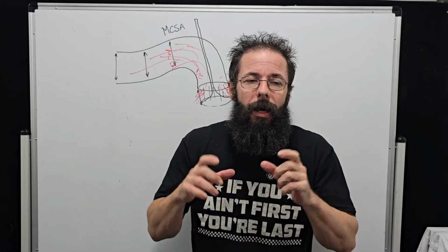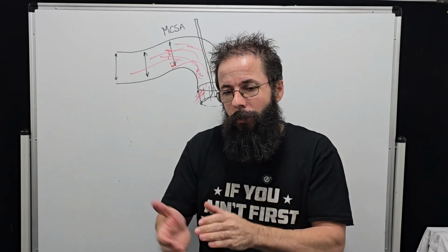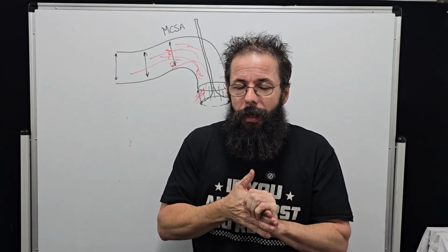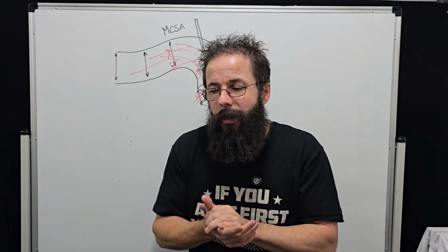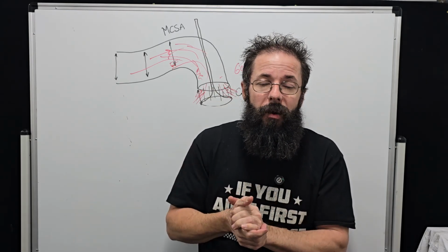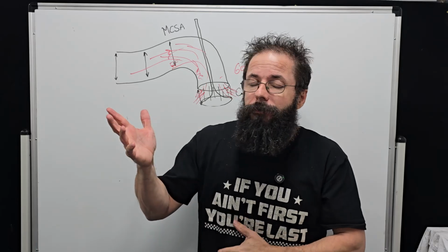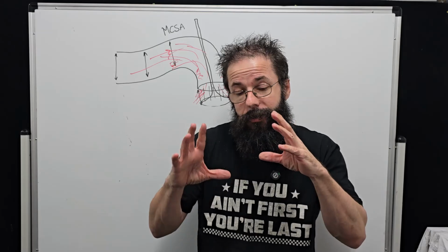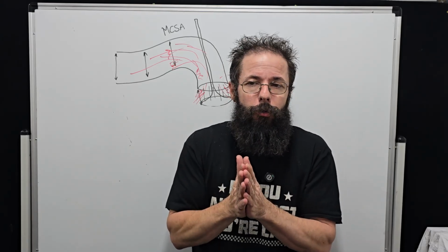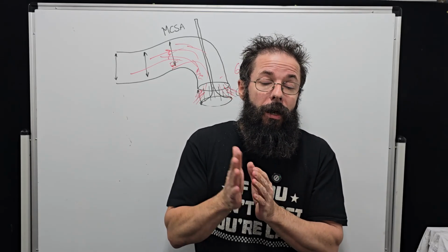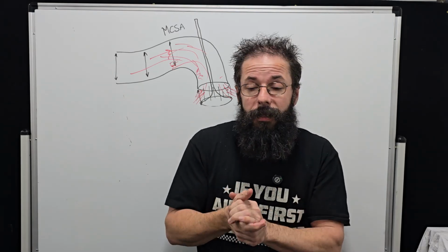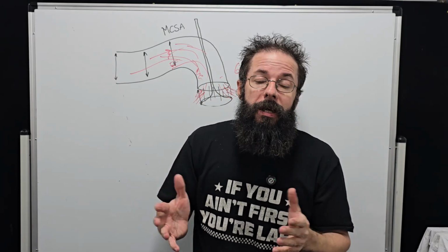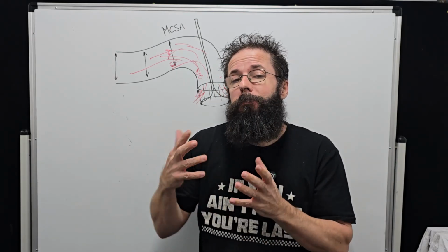The idea was the port was too big for low RPM, so they'd block one port and then open it up. Never worked really well, hence why manufacturers moved away from that and went into variable cam timing and stuff like that. But yeah, so the question was, how close is Pipe Max on its CSA? And again, I tend to go on the slower side depending on what head it is, or we actually weld the pipes up.